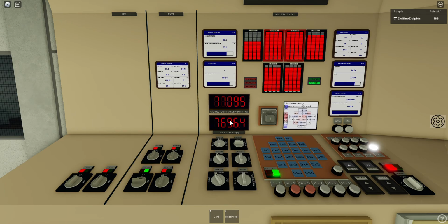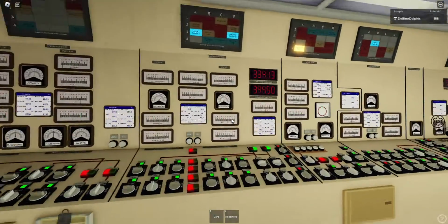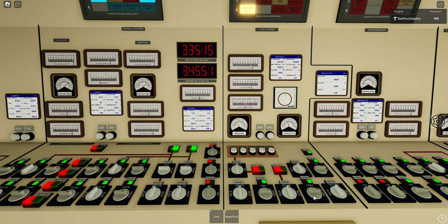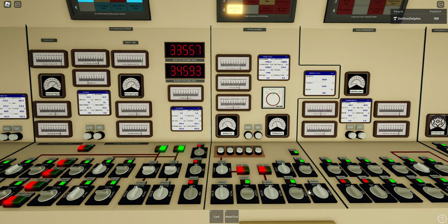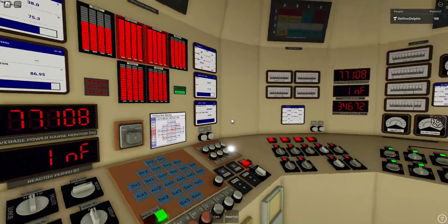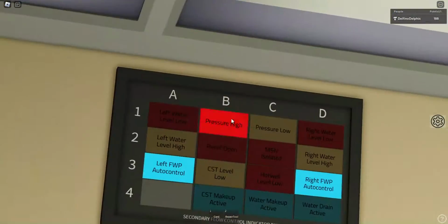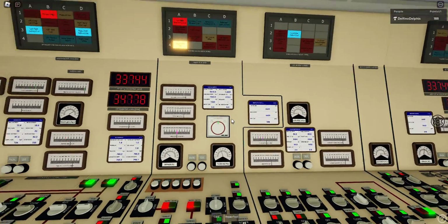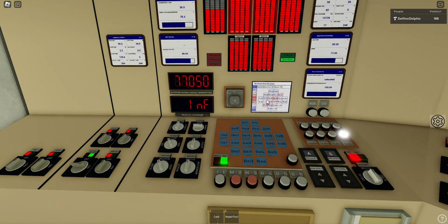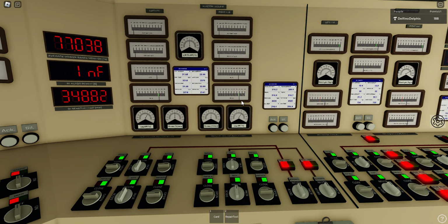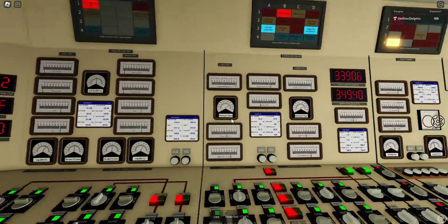Now it's swinging around. So probably when you are doing manual control, this is what you want to do, that you change the steam demand with the turbine valve, but then once the reactor reaches the lowest point or the desired point, then you will have to adjust it by your reactor control, or possibly you might want to adjust it with your cooling. This is another important thing.